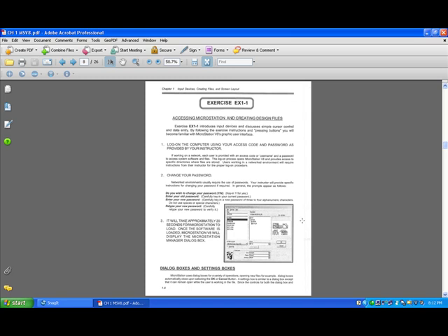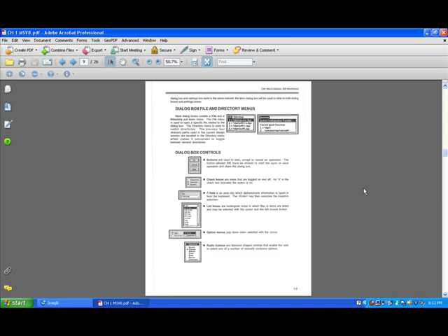Dialog buttons and settings, basically just the ability to bring things up. It shows you the different types of dialog boxes and check boxes. One of the things that we emphasize here is when you bring a tool up in MicroStation, you don't need to drag it off or close it. When you grab your next tool, it overwrites the previous one. So we try to eliminate as much motion with repeating or having to redo things as possible.